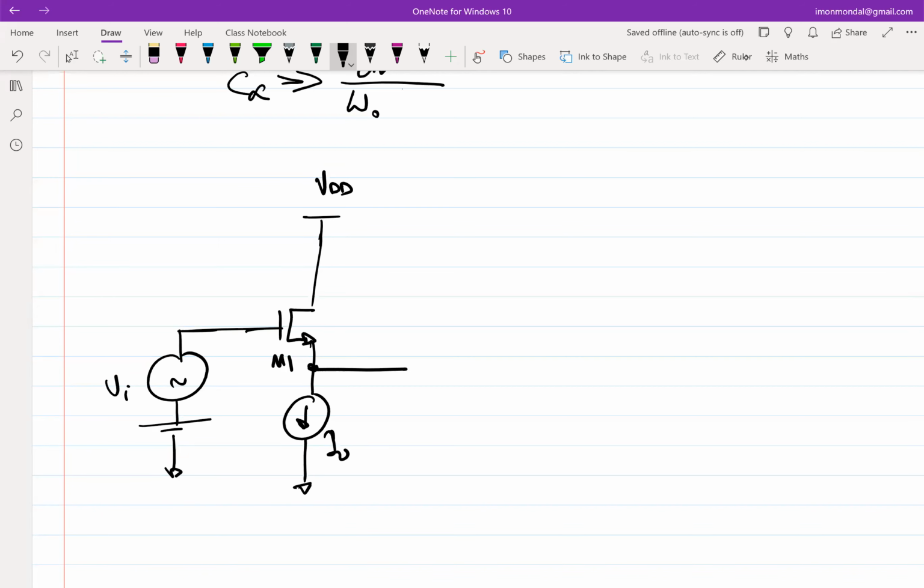And we also saw that if this is Vs, right? So what is Vs with respect to Vi incrementally? Same, right? So current cannot change. So if Vi changes, Vs also has to change accordingly, because incremental VGS has to be 0, right? Or the total VGS has to be constant. Okay, fine. So this is kind of a source follower, right? This is a source follower architecture that we have studied before the midterm break.